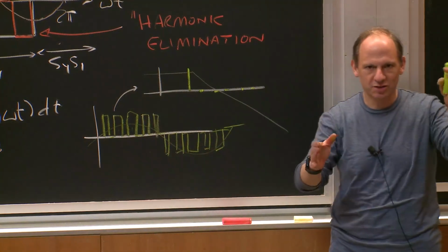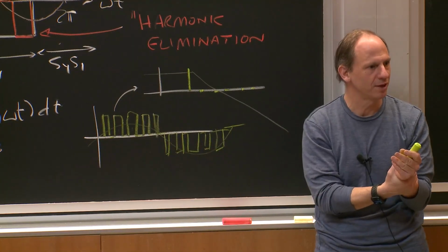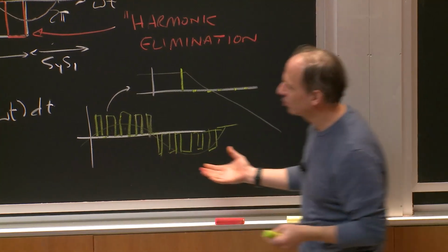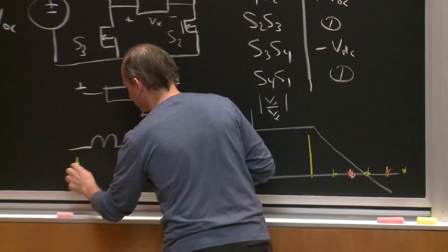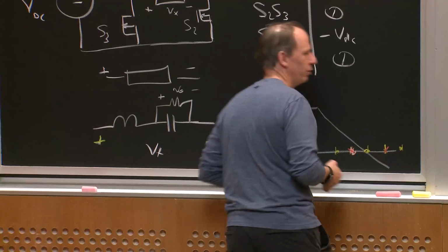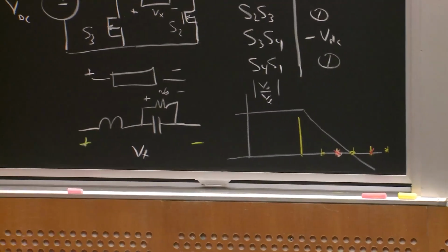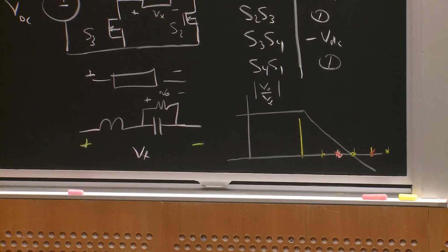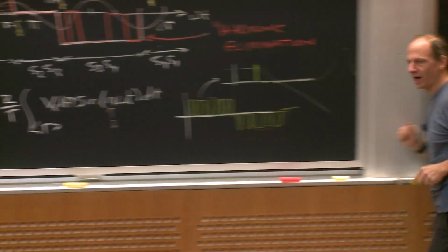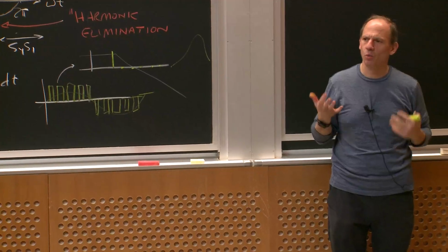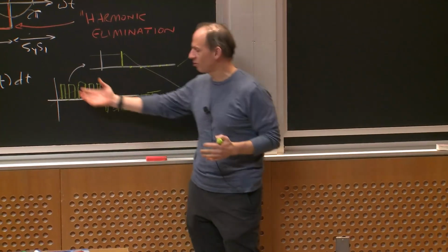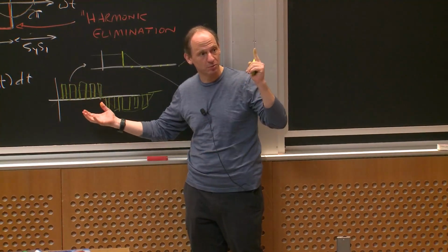That suggests there's a bunch of high frequency stuff there, right? So if I look at the original waveform Vx, in fact, if I looked at its total harmonic distortion, it actually is higher. What I'm doing is killing off the low frequency stuff, and then really growing the high frequency stuff, right? So it's not like my waveform actually has less harmonic content. It actually has considerably more.